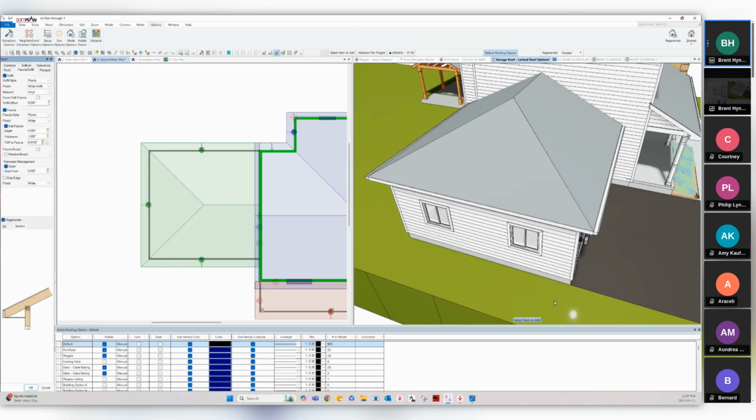So it's going to be levering off of the top of that point, which means I'm going to likely increase my top to fascia number, okay? So if I'm in my roof options here, and I go to my heel height and I lock that in, and then I increase my pitch on this roof to say, let's try an 8-inch pitch.